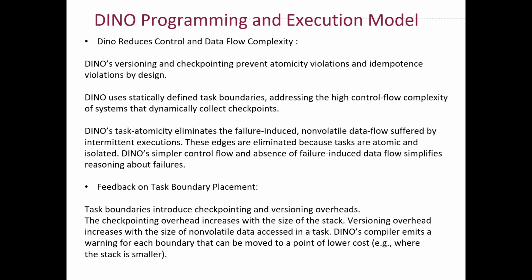And in this way, you ensure data consistency across reboots. Now, coming again to control and data flow graphs, DINO's versioning and checkpoint prevents atomicity violations and idempotence violations by design. How? We discussed the data versioning and the checkpointing. Now, DINO uses statically defined task boundaries. So this addresses high control flow complexity of systems that dynamically collect checkpoints.